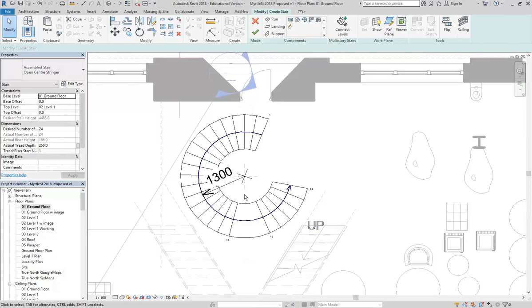If you want to get into all that Fibonacci stuff, it's pretty interesting how you generate a true spiral. Don't ever do that. Don't ever do a true spiral. You can do all that Fibonacci, but do it with the golden mean and look at how you can draw them. They're not a true Fibonacci curve. The ones you do using the golden mean are a series of arcs that look like a true spiral, but they're not. But they're the ones you should use. They're much easier. True spiral is a pain.